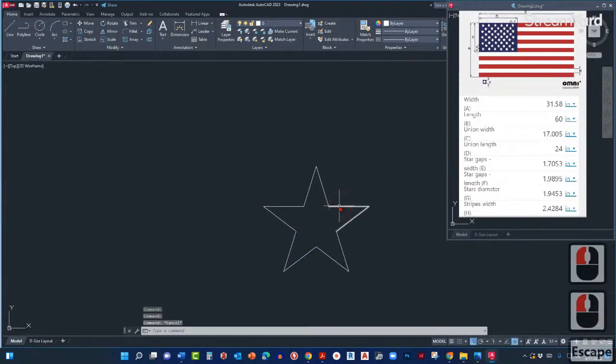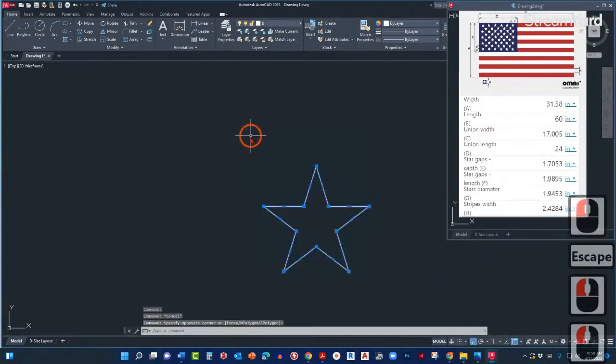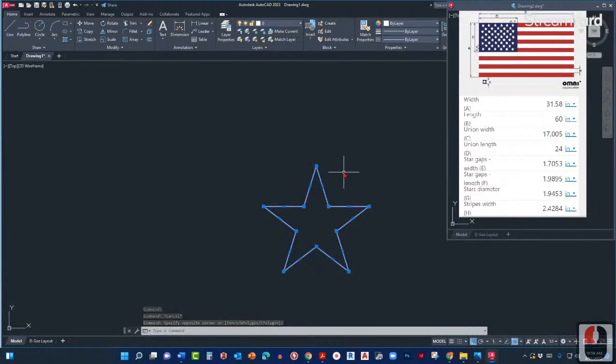Okay, so our line is almost ready, but I can see that some of these objects are divided. In order to combine all of these into one single polyline, let's simply select all of the objects for our star, and let's use another command called join. The shortcut is J. We press enter. You can see that over here, 9 segments joined into one polyline, which is nice.